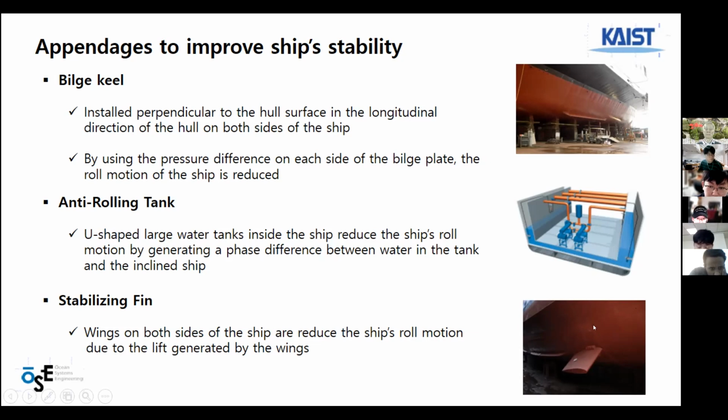Yes. The stabilizing fin can rotate this plate. By rotating this plate, it can generate lift or down force. So by this force, the ship's rolling motion is reduced.